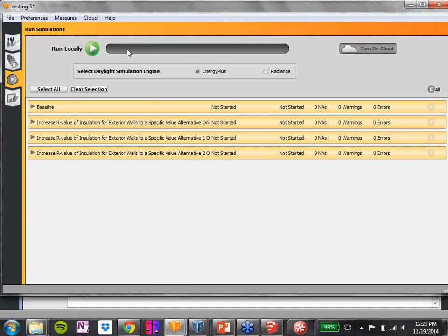It will show 0% completion for pretty much a long time, and all the models will finish pretty fast on each other's heels. So even if it says that it's 0% complete, you'll see that these will be running. Hit start. And so just pay attention to that. Since this is a 4-core machine, I've got 3 going and one that's going to wait in the queue until this one's complete.